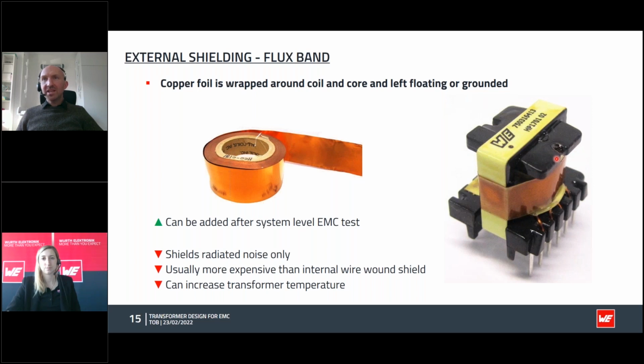To have a winding in the transformer, we need wires wrapped around the center leg. Here we don't wrap around the center leg, we wrap entirely around the outside surface. So it's not a winding, it's a flux band, and it only picks up stray flux flowing outside of the transformer. This is why we can short this and it doesn't constitute a winding.